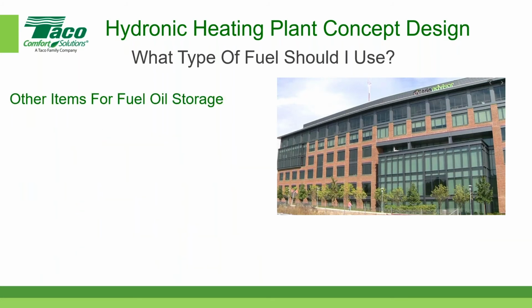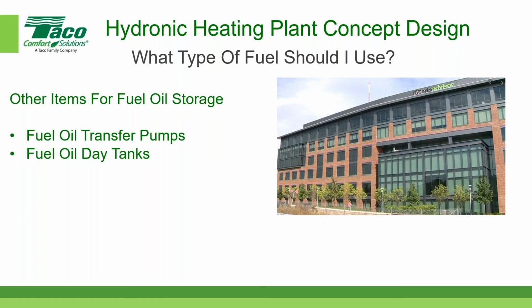Okay, so one other thing I like to point out about other items for fuel oil storage. If you opt for fuel oil for your building, you have to take into consideration that you need a fuel oil transfer pump system, because let's say you had fuel oil storage and it was underground. There are specific code requirements for fuel oil storage tanks underground. That's why I put the code issue up front. I won't review those, but ultimately you need to transfer that oil from the storage tanks to typically a day tank. So a day tank is a relatively small tank that's inside the building. And usually the day tank could be as little as 200 or 300 gallons, that sort of thing. And the whole idea is to pump the fuel from the storage tanks to the day tank and then feed the boilers from the day tank.